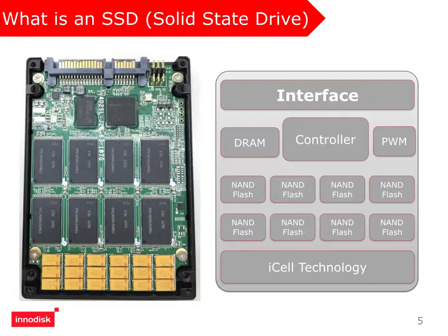Here you can see the structure of an SSD. It is mainly composed of NAND flash chips and a controller. Other optional components can also be built into it if necessary. Once the controller receives the data from the host, the data will be written into the flash chip. The difference with SSDs is that old data must be erased before storing new data.